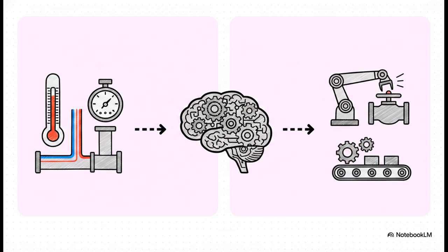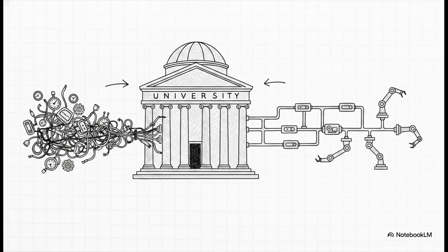This is the mechanism that receives the data, compares it against whatever your desired target is, and instantly makes a corrective decision. So if the flow rate is too low, the process controller automatically opens a motorized valve just a tiny bit wider to compensate. Or if a chemical reaction starts running way too hot, it immediately triggers the cooling system. And it's doing this thousands of times a second, tweaking heaters, valves, and belts without a single human ever having to step in.